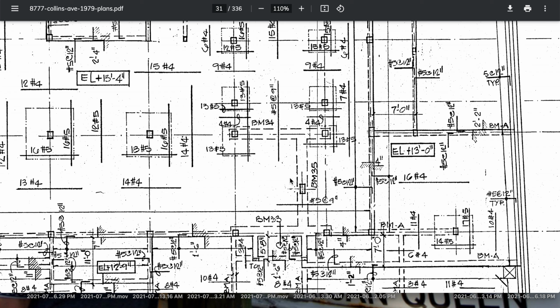That's awesome. Because it gives you an idea how you're getting one beam over here. Now this, wait a minute. All right, so this one, the loads can be put on top of this one, and this floor deck can be put on top of this one. But then they did another transfer beam down here on top of this one to transfer into there. That's quite a few transfer beams going on. It's kind of pretty. That's why I said it's nice.